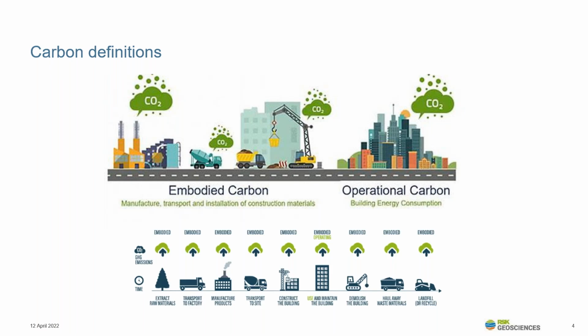Operational carbon is the carbon that comes from the energy, the heat, the lighting, and anything else used in the operations. Following advances in reducing the operational carbon, recent data from the World Green Building Council has indicated that the embodied carbon is now becoming a larger proportion of the building's overall carbon footprint. So while I'll use the term carbon throughout this presentation, we're looking at carbon dioxide equivalent, and this actually accounts for carbon dioxide and all the other greenhouse gases as well, methane, nitrous oxide, etc.